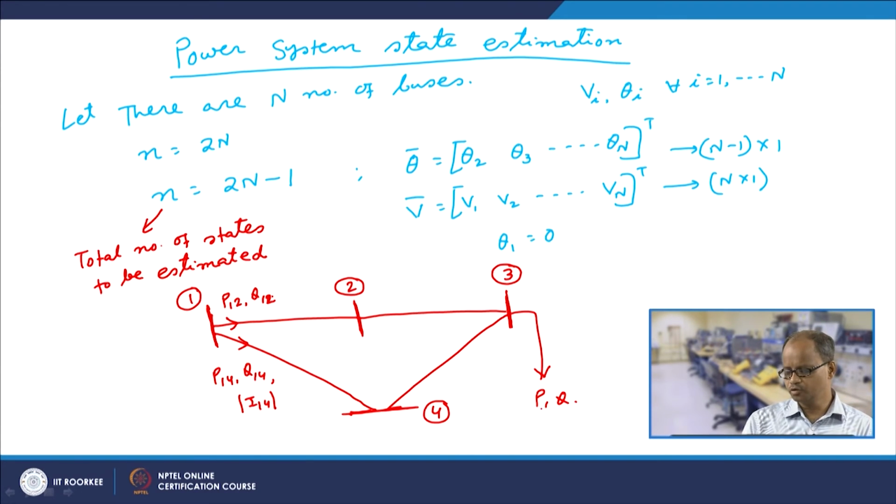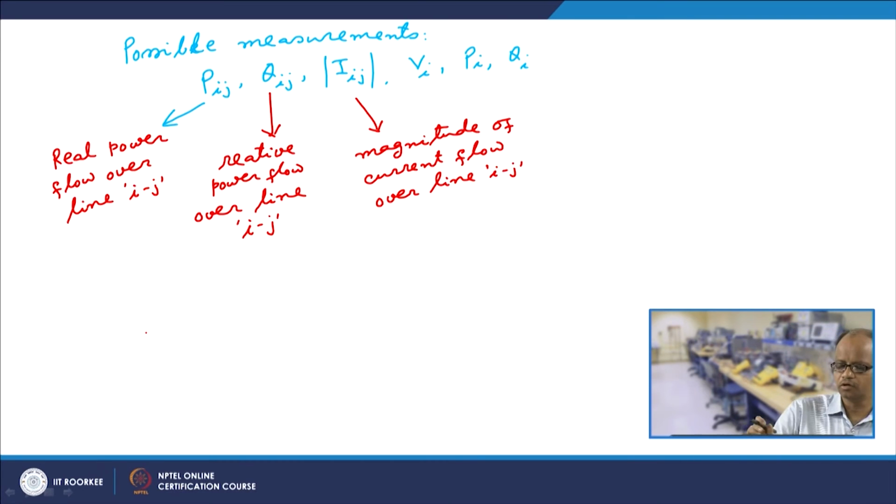Then we would be able to measure the amount of load, and our measured values of Pi and Qi would be the negative of these measurements. Similarly, if I have a generator here, I can put another wattmeter, and then we can measure the values of Pi and Qi from this particular generator.